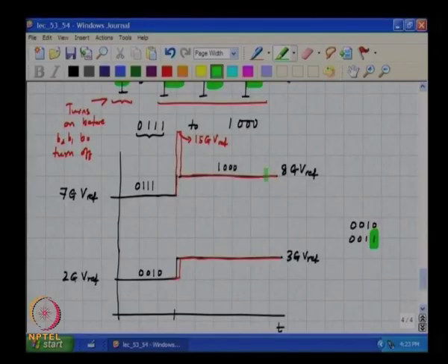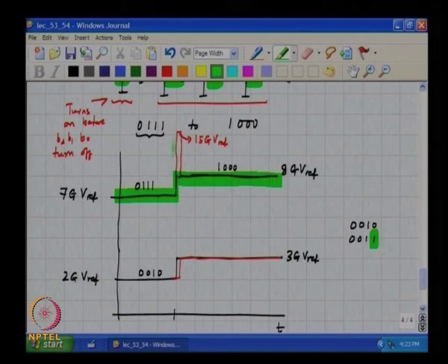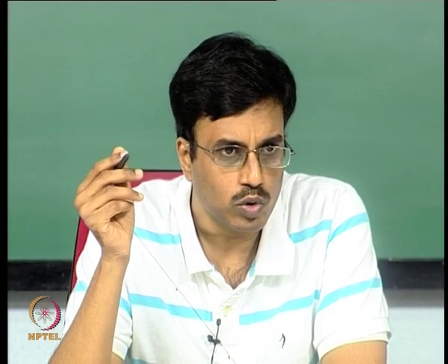So basically one thing that's apparent is that the actual waveform coming out of the DAC is the ideal waveform plus some error which you can call a glitch, correct? Now if the DAC was a perfectly linear system, in other words, if you are able to relate the output waveform to the input sequence through a linear system, whether the code goes from 7 to 8 or from 2 to 3, the size of the step and the nature of the change in the waveform must remain the same, correct. What do you see here now?